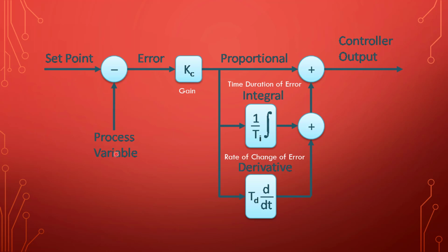Here we have a process variable that we're measuring, and we have a set point where we want it to be. This is the comparator, and the difference between where we want it to be and where it actually is, we're calling the error. And we have, in this case, a gain, so we're going to maybe amplify that error, or maybe not. But I may have a proportional controller here, like we just looked at, and that's going to control our output, the correction devices.